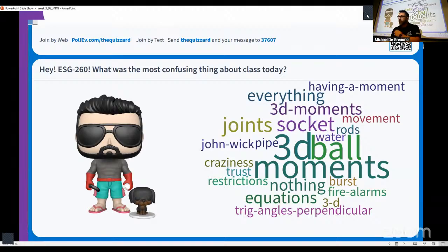So what are the reaction forces? The ways that we are resisting that motion. Reactions prevent motion, right? In 2 dimensions, we talk about a pin, and a pin allows you to have a moment. We rotate around a pin, but we don't move left, right, or up and down at a pin. A pin holds us in place, but we can spin around it. Same idea for a ball and socket joint. It's the 3D version of the pin joint, okay? It's a 3D version of a pin.